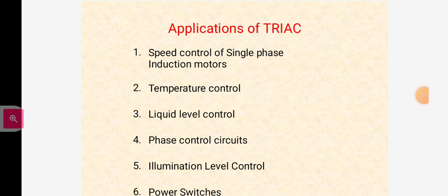A triac needs a single heat sink of slightly larger size, whereas an equivalent anti-parallel thyristor pair needs two heat sinks of slightly smaller size. A triac needs a single fuse for protection, which simplifies construction.